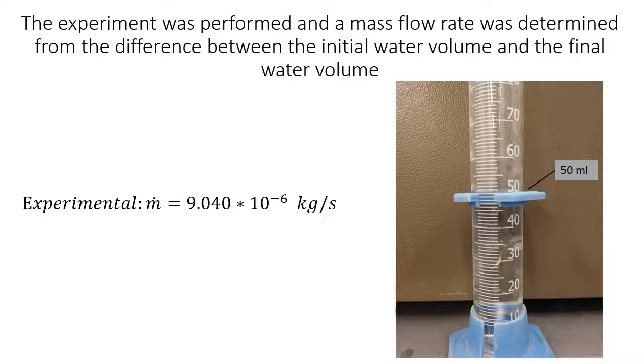After performing the experiment and leaving our system out in the sun for 2 hours, a final water volume was found to be 50 milliliters, which equates to 9.040 times 10 to the minus 6 kilograms per second of water that was evaporated by the system.